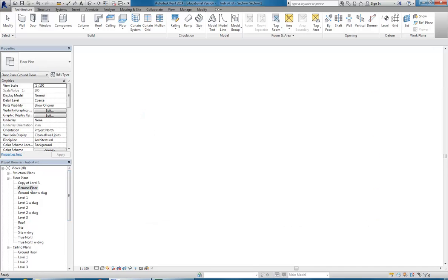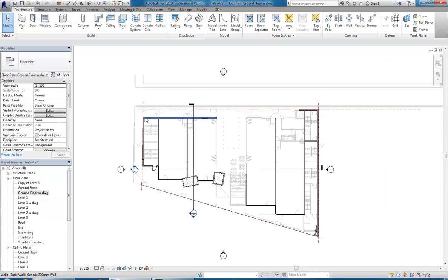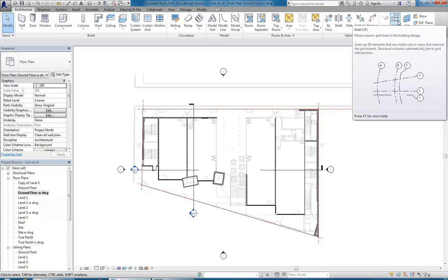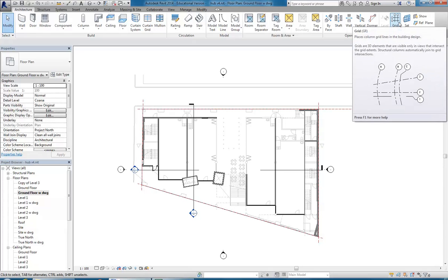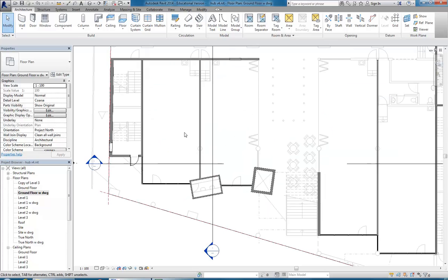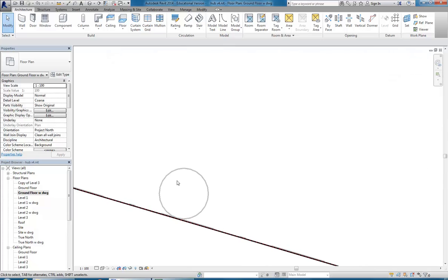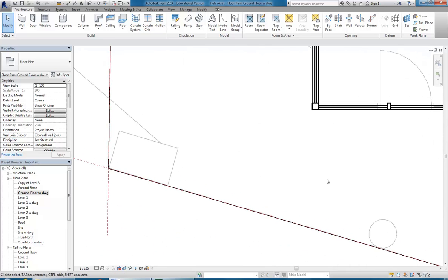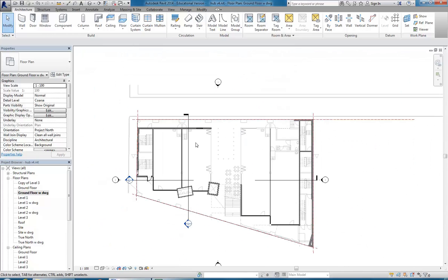Looking back in the floor plan, you can establish measurements in the plan in a similar way using grids. And so if you haven't used the grid tool, it's really useful, especially if you've got columns. I know with the buildings that you're working on, most of you will have columns. And so if you've got columns, and I'll just show you here, like I do in my floor plan, you can see these columns, which are set out following a pattern. Then you should make a grid first for those.